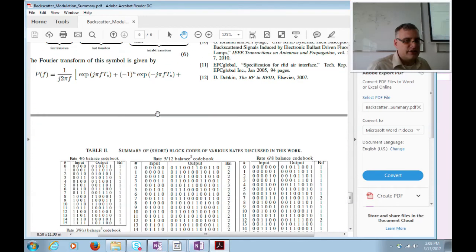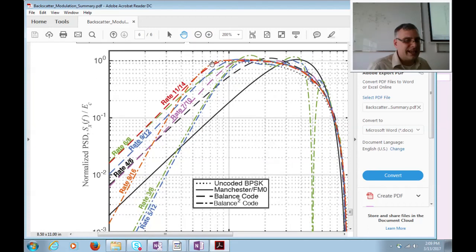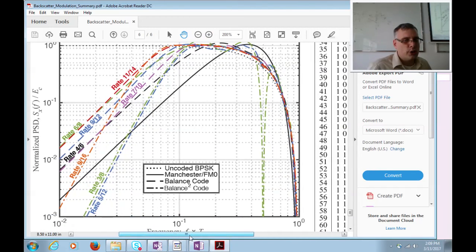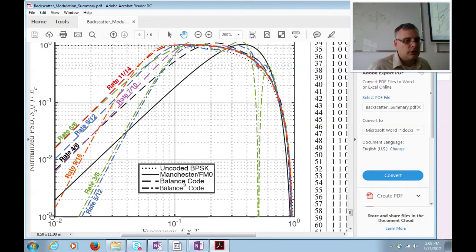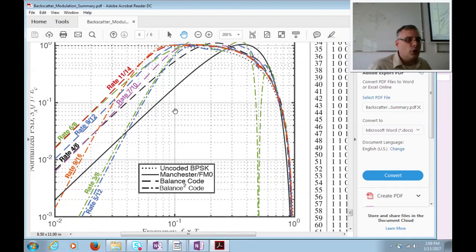And I have another plot here, a logarithmic plot, which you can take a look at as well. It's that exact same plot, except now we're showing logarithmic frequency on this axis, and then logarithmic power spectral density on this axis. And see the uncoded BPSK or uncoded signals? That starts here on the logarithmic axis, looks very flat, and then starts falling off the table, boing, boing, starts getting those side lobes right after that. Here, all of these dive towards 0 on this log-log plot.